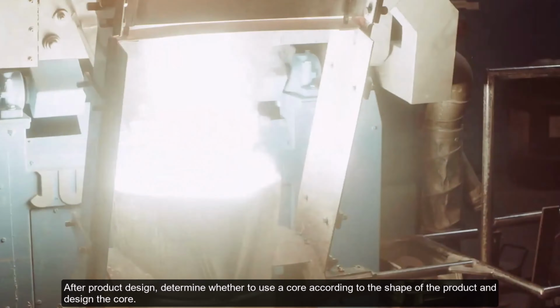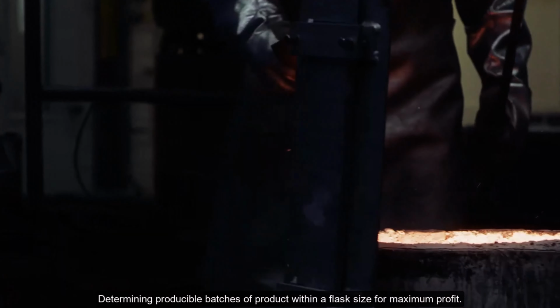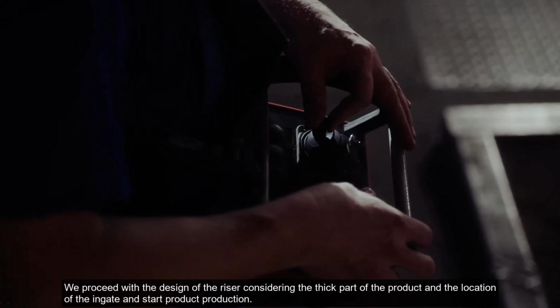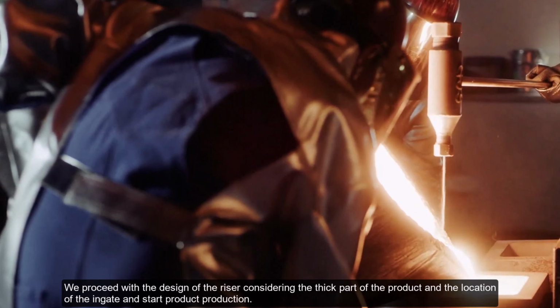After product design, determine whether to use a core according to the shape of the product and design the core. Determining producible batches of product within a flask size for maximum profit. We proceed with the design of the riser considering the thick part of the product and the location of the ingate, and start product production.